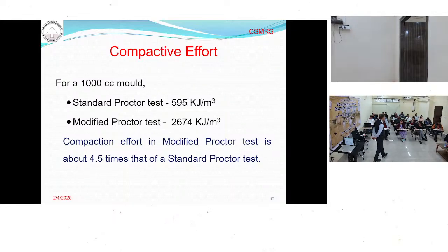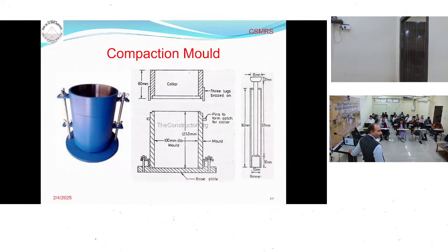Second, what is the process? How do we do it? Yeah, this is your mold. You take the sample and air dry it completely, 4 to 5 days, and take 90 mm passing sample and add some water. Now the question is how much water should we add?